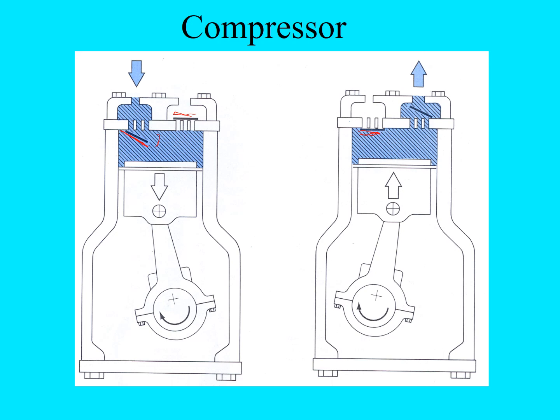The refrigerant is being moved to the high side, and the pressure is being created by the restriction in the line to the evaporator. So that's where the pressure is being built. It's not being built inside the compressor. It's because of the restriction. The compressor is just moving the vapor.